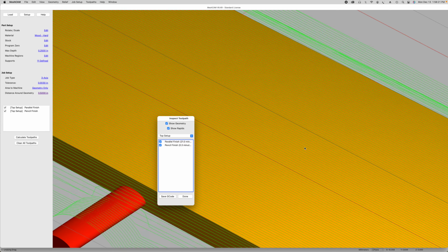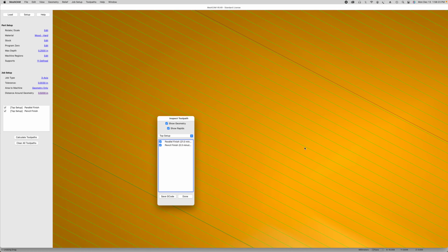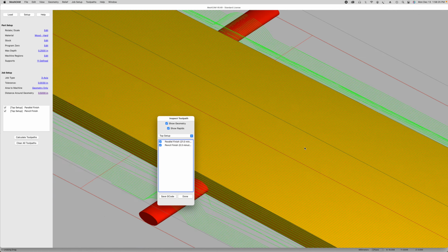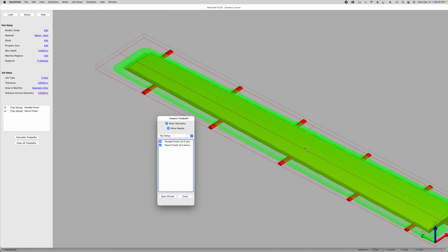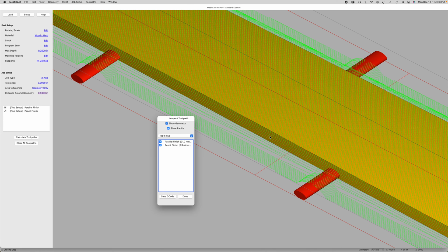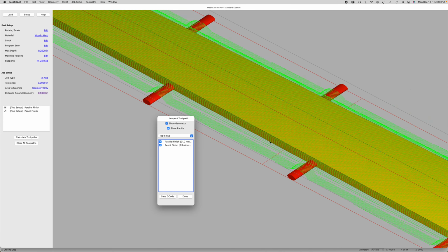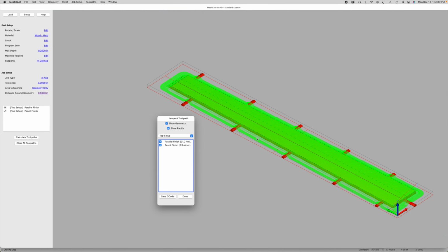If you look really closely, it's individual green lines. Those green lines represent the center of the bit as the spindle is moved back and forth along the y-axis to carve that shape. However, what it wants to do is carve the sides as well as both ends.